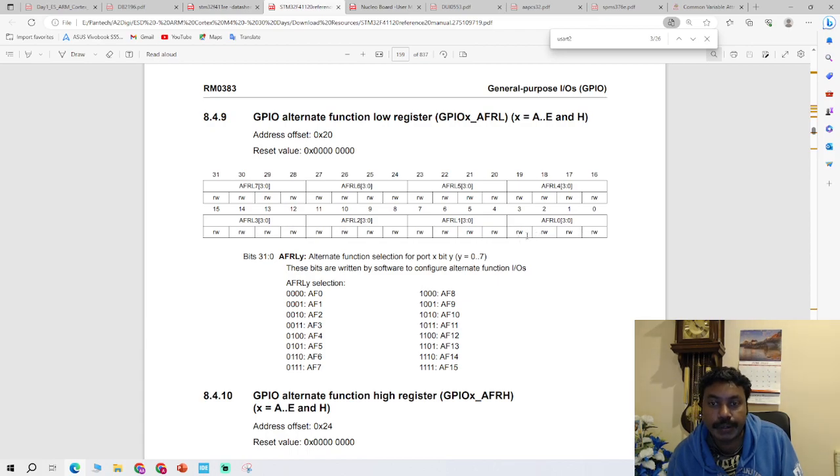So you need to go with, that's port A, pin 1. As you know, STM32F411 has 16 bits of this GPIO port, so you can use that. So port pin 1, pin 2 and pin 3. So you need to use these 4 bits. From the functional mapping, you learned AF7.